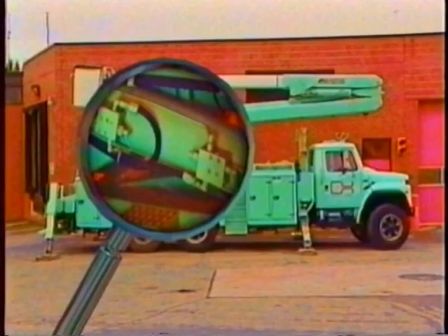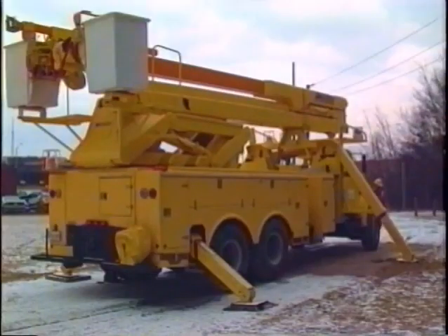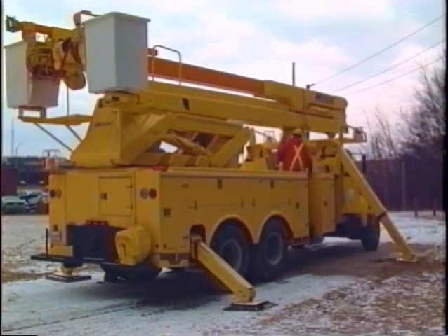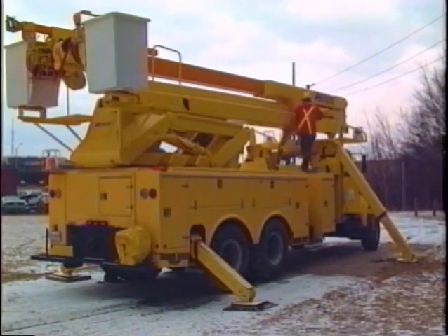Earlier in the program, we talked about the holding valves, which are an essential part of the safety systems of a bucket truck or RBD. Occupational health and safety regulations require that you inspect your vehicle's holding valves every day. To check the holding valves, you follow 3 basic steps, repeated with the components in different positions.